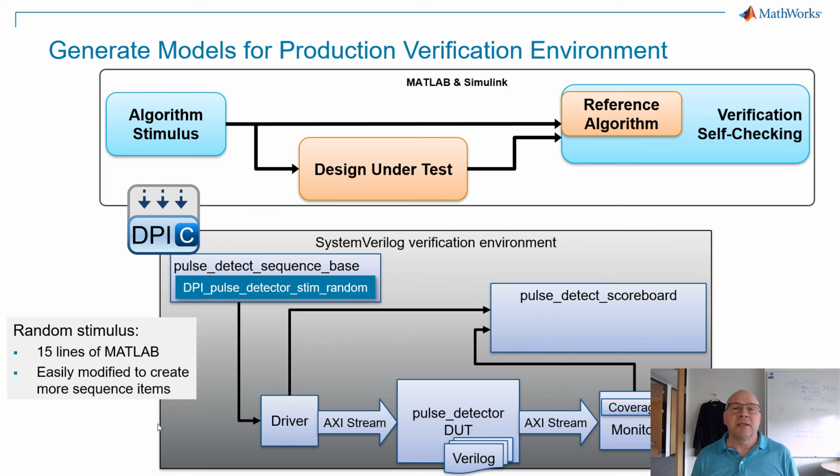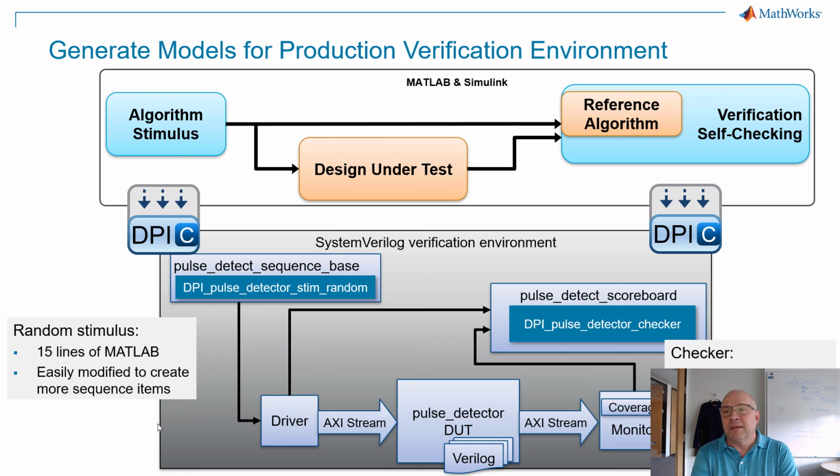That is, you can generate what we call SystemVerilog DPI-C components. That's the direct programming interface, I think, and that's an API that the leading simulators have that lets you bring in components. So it could be something used for a checker, or in this case, it's for the actual stimulus, which you would have. So a lot of customers we found have been really attracted to this.